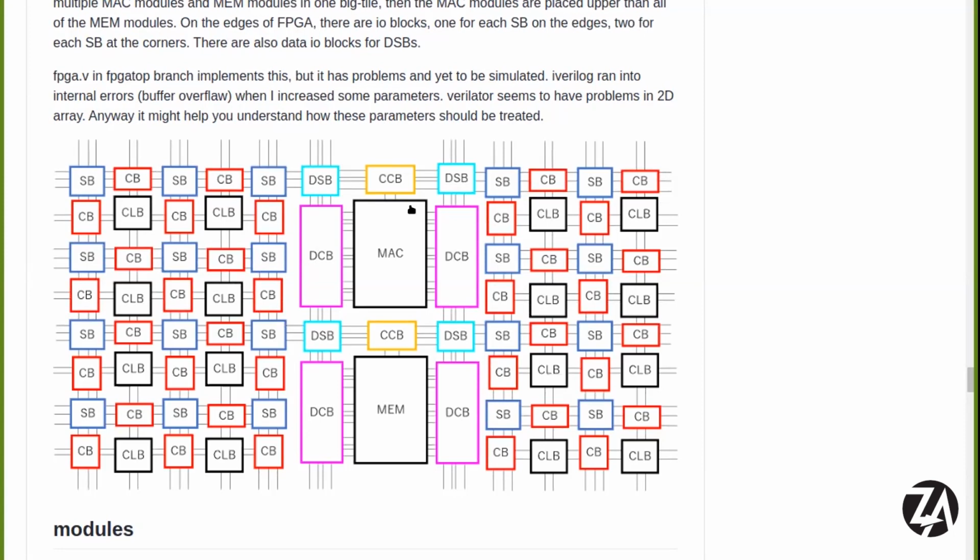But then as time went on, the tools improved a little bit, and we kind of understood how to avoid the constant nagging of density value too low and so on. And we ended up being able to synthesize, for example, a whole CLB tile out of the CLB block here and the two connection boxes and a switch box into one hardened macro. And so then that became the final building block. Okay, and then you were able to duplicate those in a regular pattern. Yeah, and that's what I'll show you in the next shot.